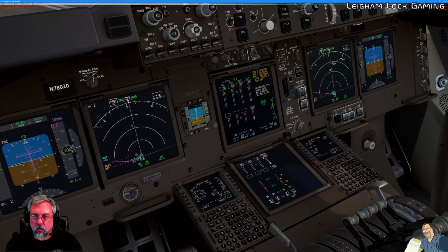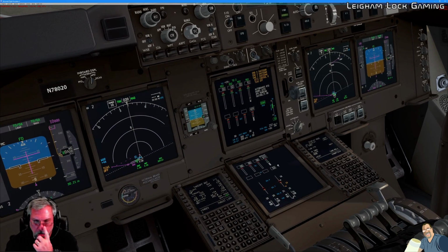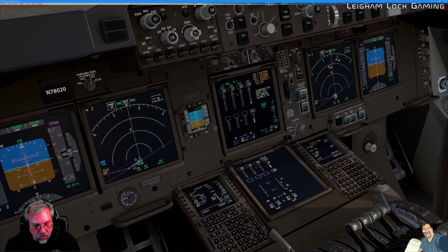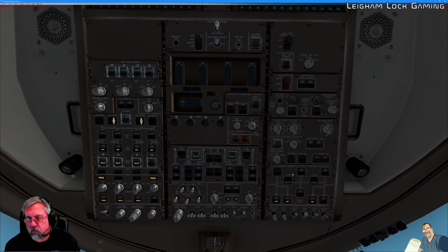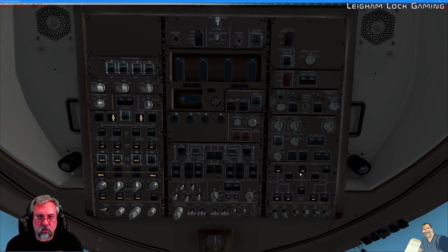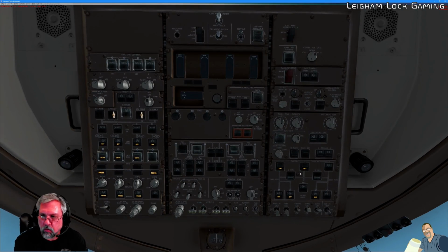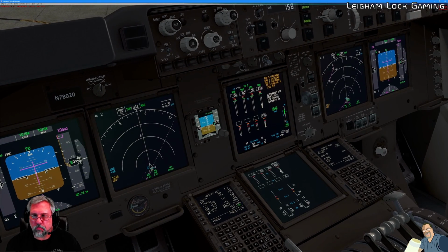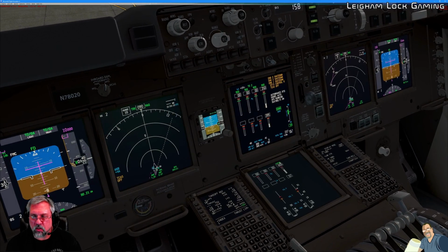What we watch here, or at least what I watch, is notice the auto start on top of engine 4. We want to wait till this is running, and actually this is a slow start. One thing that I did forget to do is go to the overhead console and turn off 2 packs just so that bleed pressure is available to the engines to assist with startup. That's why that engine took so long to start. Waiting, auto start says running, so that's good.